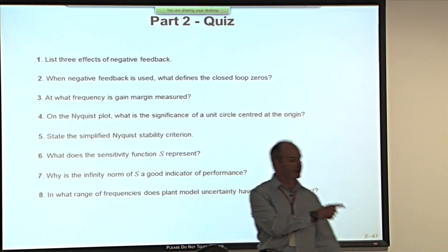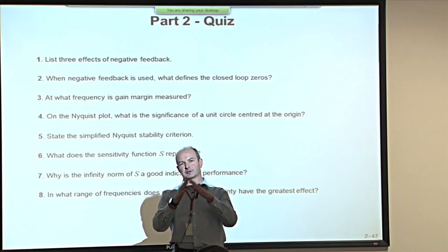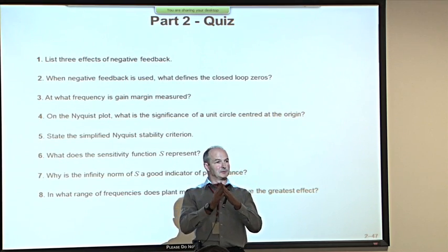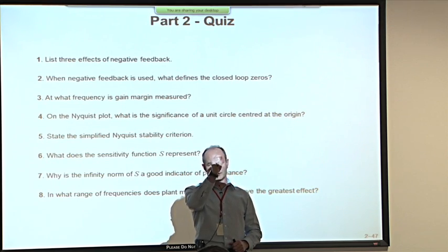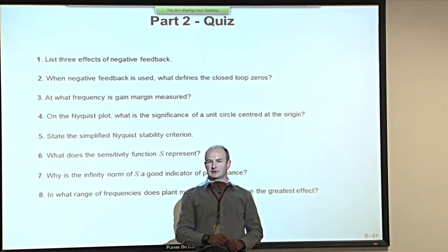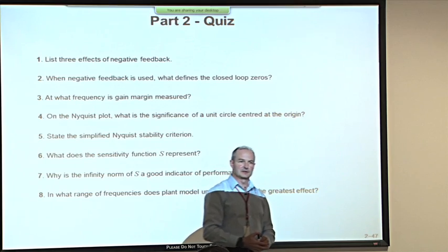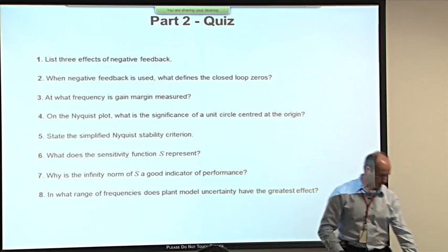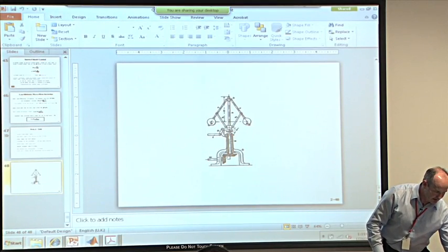Yes, you're close. It is that range of frequencies, actually. It's the range of frequencies where S and T are approximately equal to one another, but most importantly, that's the gain crossover frequency. It falls right in that region. The open loop transfer function has unity magnitude right around there, and that's where the stability of the loop is decided.